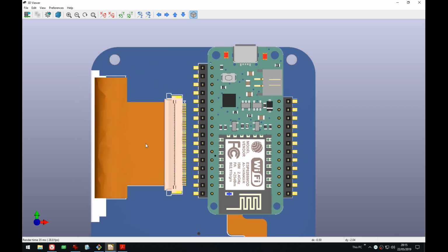You can route here, but you can't really place components under the flex because it will just not fit otherwise. Or you would have to put it way in the back, not directly under, because this is where it starts going down to the connector. So there is some stuff that might have to fit over here, like the backlight control, which is just a SOT23, so that's fine.